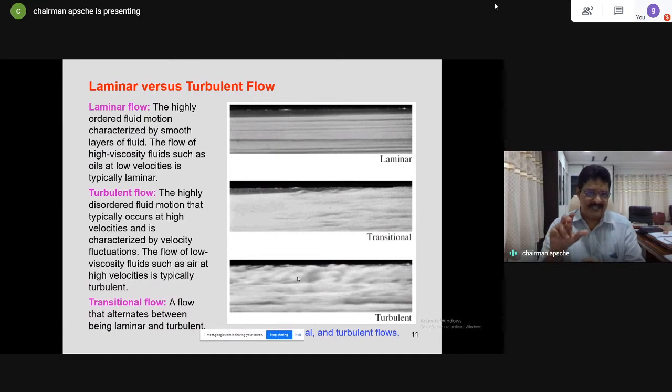That is, we set the fluid flow such that it moves at very low speeds or velocities, and you inject some colored ink at the center of the pipe and see the streamline of the ink going exactly through the center. The colored ink was traveling along with the fluid exactly at the center line. That implies that the ink is moving highly organized. It's not randomly mixing with other layers of the fluid molecules, and it is following a particular flow path, right?